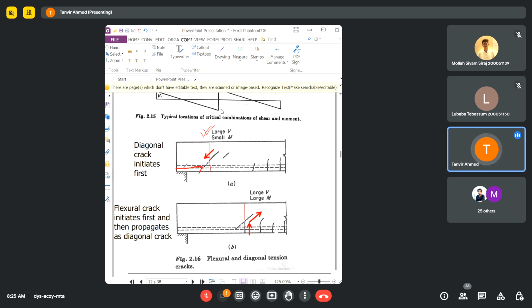If the crack moves in this direction, the failure will be less rapid. So this is in a way good for the beam. Because of the presence of the longitudinal reinforcement, the shear failure can be delayed to some extent, but it's not the ultimate solution. Obviously, you still need the shear reinforcement to hold these cracks from propagating further.